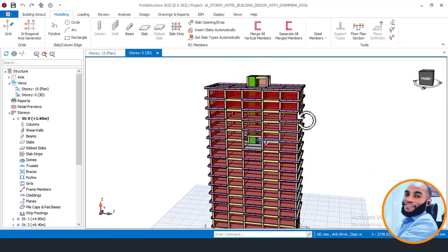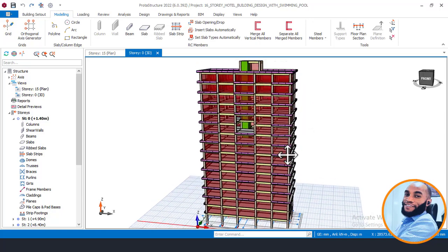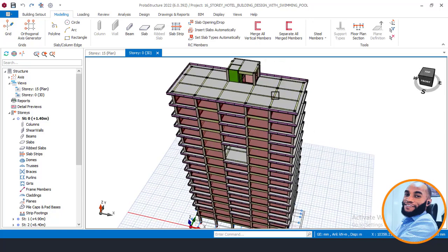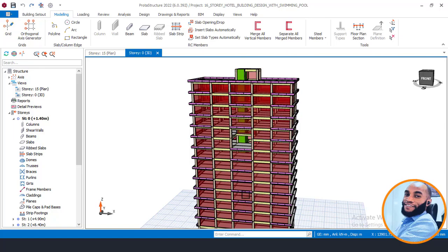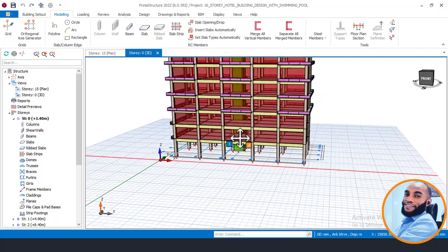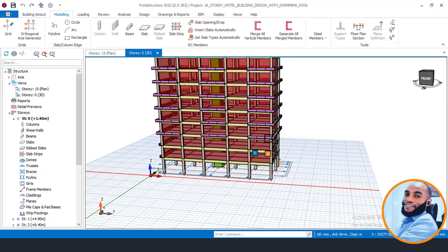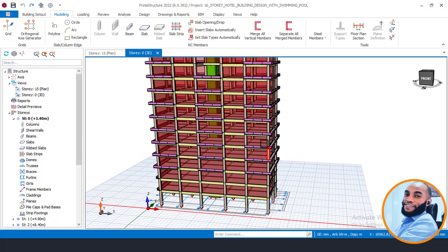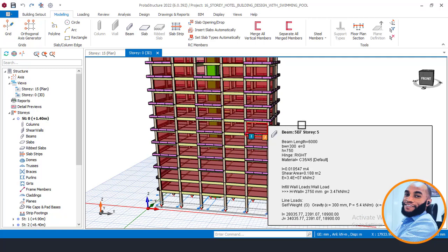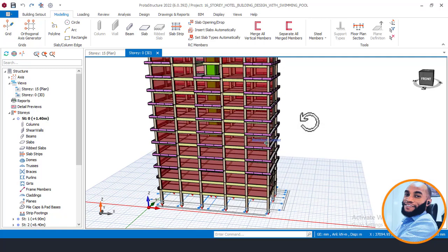Okay. Now the question that will come to your mind is, if I am to reduce my load based on waffle slabs, and knowing that I have solid slab right from the top floor here up to the last, which is this ground floor here, am I to just remove everything about solid slab and use waffle slab in all? Well, most people decide to do that, but most of the time they decide to start from the place where live load reduction is meant to be applied, and the height at which you are meant to apply live load reduction is 10 meters.